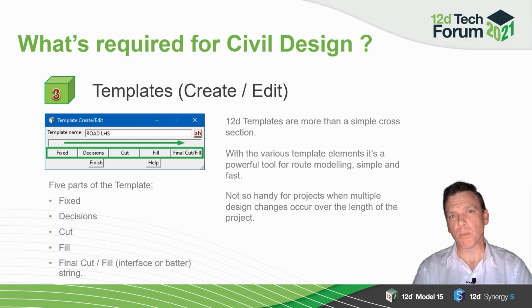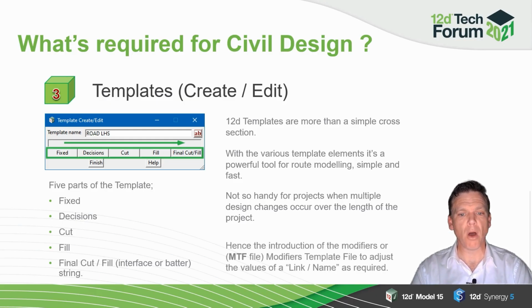The problem is obviously that over the length of the project, a number of changes might occur, and it sometimes is handy actually not to create lots of templates. This is when the MTF file, or the modifiers templates file, was created, so that we can adjust these links and adjust the parameters to change the crossfall, the width of the road if we wanted to. So it's really important to have an understanding of how it all goes together with the MTF file, and we will be diving into the MTF file itself.